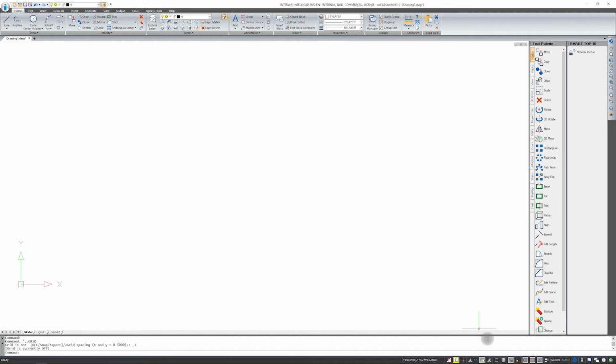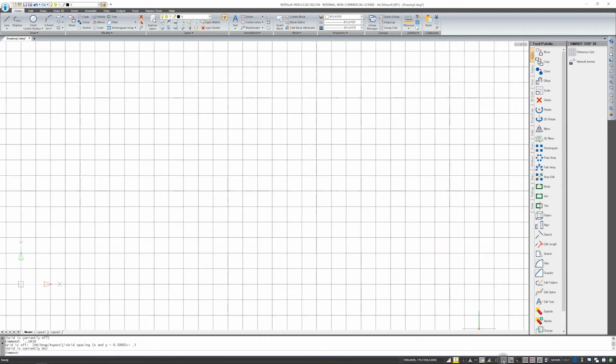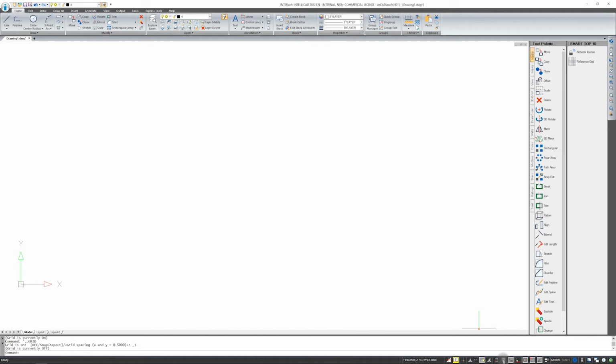The first thing you have probably noticed about the program is the grid. The grid can help you draw because it can be your modular mesh. If the grid snap is turned on at the bottom of the status bar, then the cursor will stick to this grid, and this grid will be an auxiliary element for drawing.